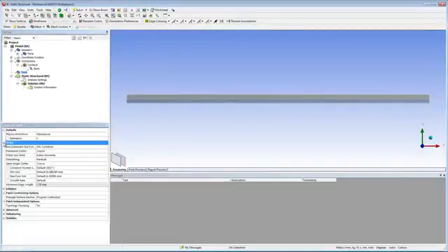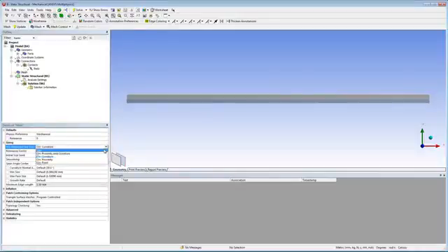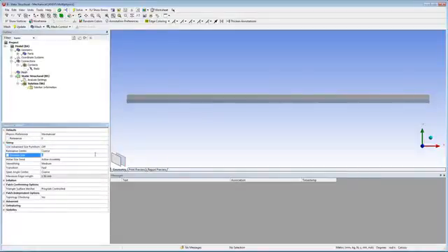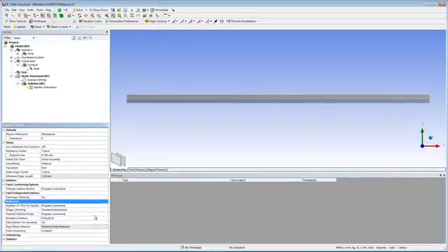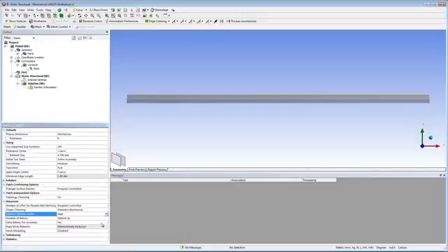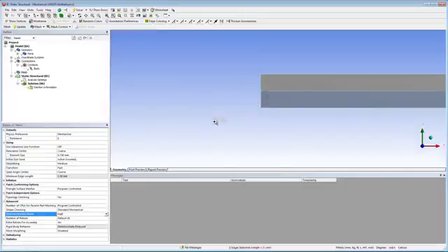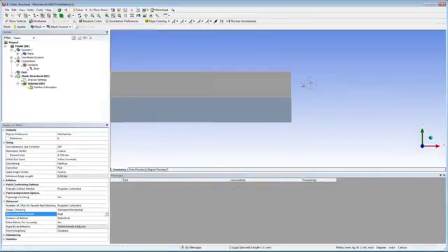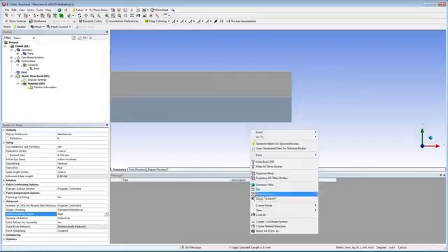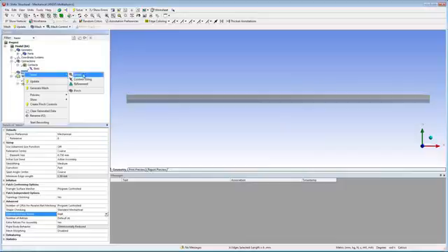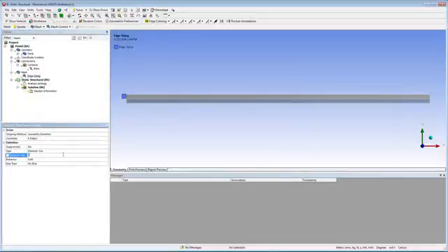I also need to prepare some mesh options and controls. I'm turning the Use Advanced Size Function property off, setting a default element size, and setting the Element Midside Nodes property to Kept. And I'm going to configure two mesh sizing controls for the edges of the model. These mesh controls help to create mesh elements that have a fixed size for the model as well as along the line of interface to lamination. Once I have completed my sizing controls, I will generate the mesh.